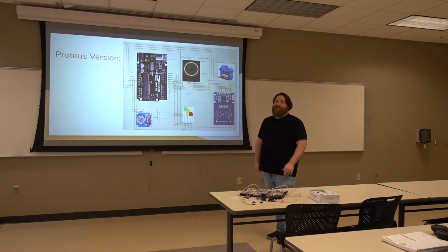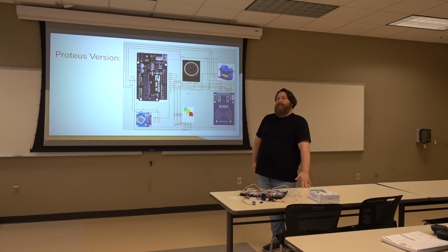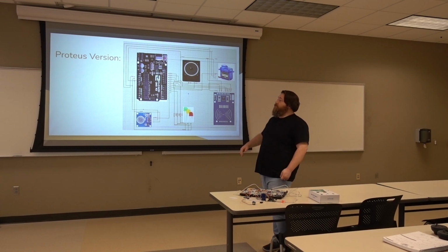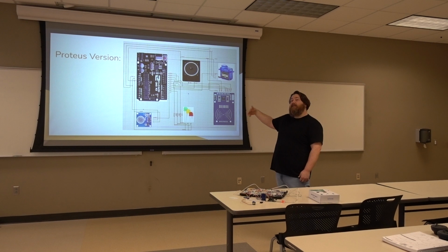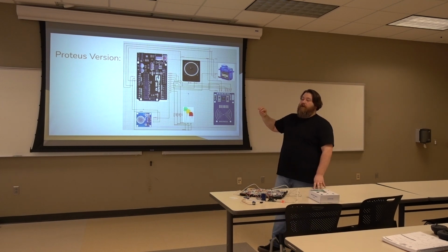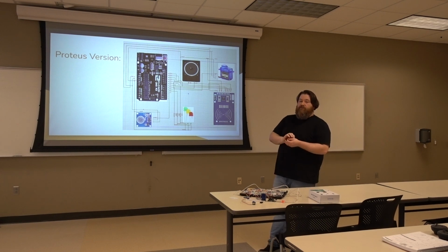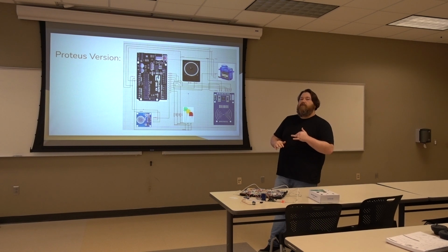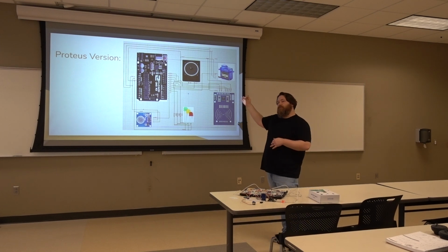I was thinking, would there be a way with the code, like you'd probably have to wire it into the building, so that if the fire alarm for the whole building goes off, it just unlocks? Well, yeah, ideally, similarly to how it was constantly looking for the RFID card, you would add maybe an if statement there. If an alarm state was active, send it to unlock. Send the servo straight to unlock. So that would just be a quick, probably 4-line code. If alarm statement equals true, send the servo to unlock.